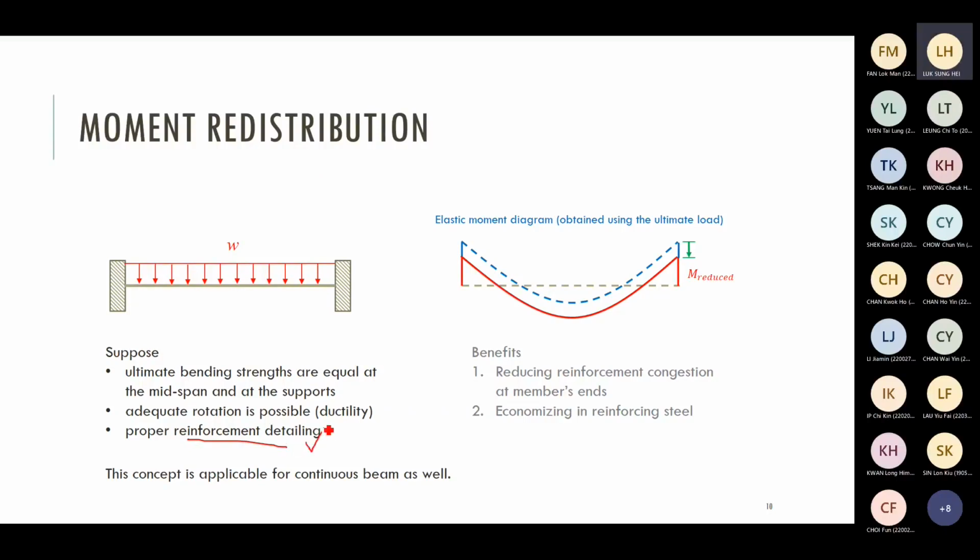If you follow some very strict detailing rules, for example, if you provide sufficient reinforcement and fulfill some reinforcement ratio, not too large, less than 2.5%, and then you have sufficient confinement, something like stirrups at the beam end. For reinforced beam, you need to provide some longitudinal bar, satisfy some steel ratio requirement, and then add some stirrups to provide confinement on the two sides of the member.